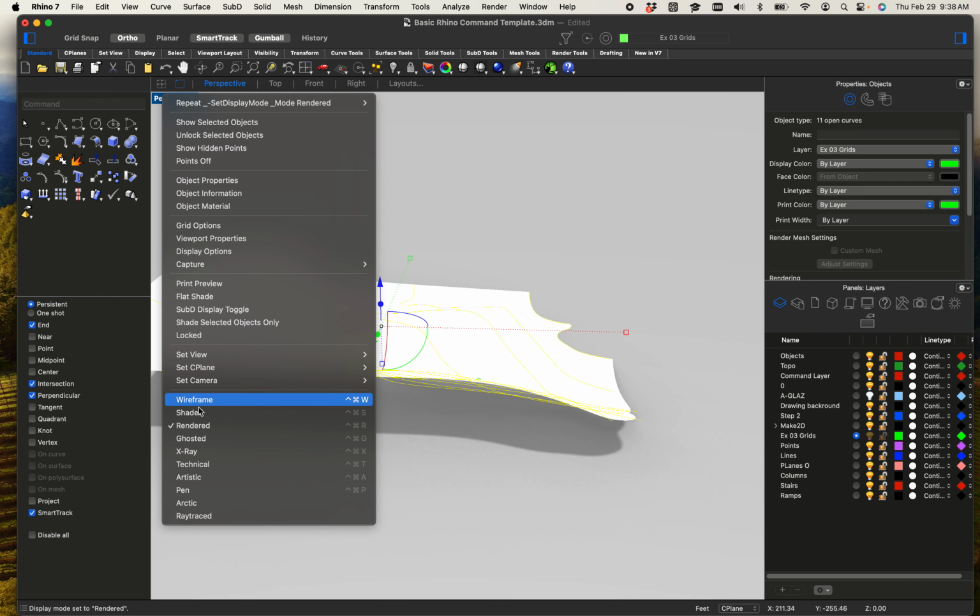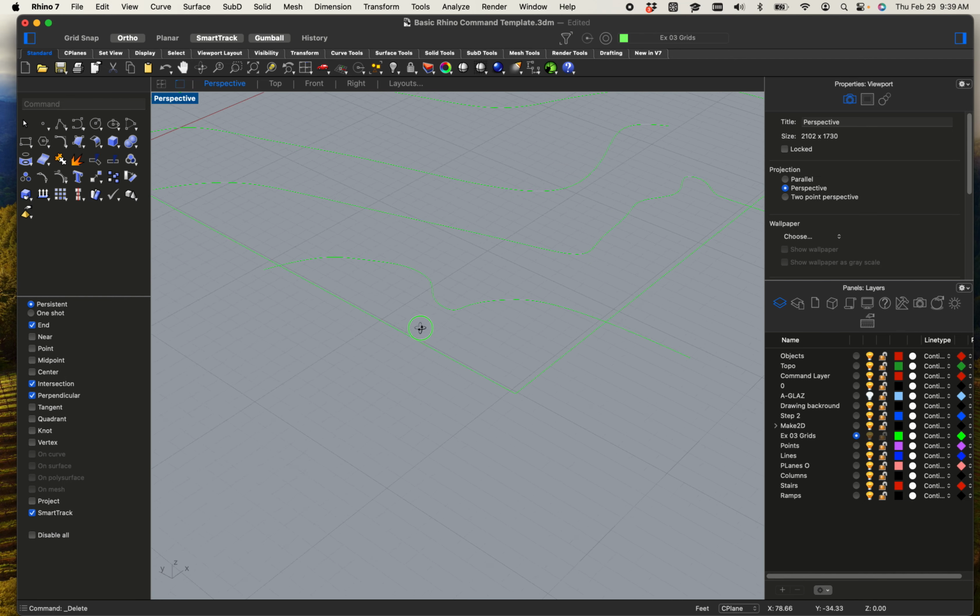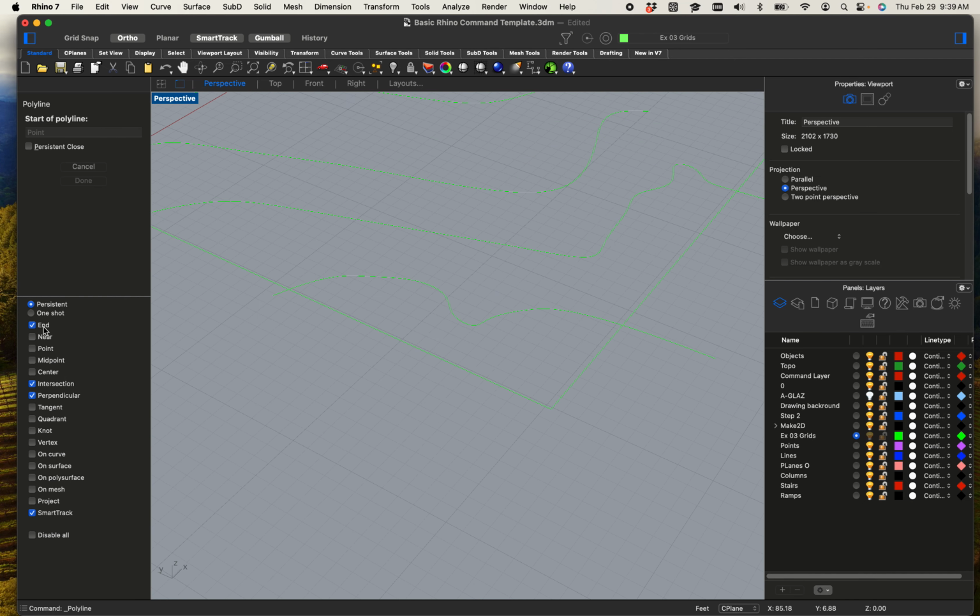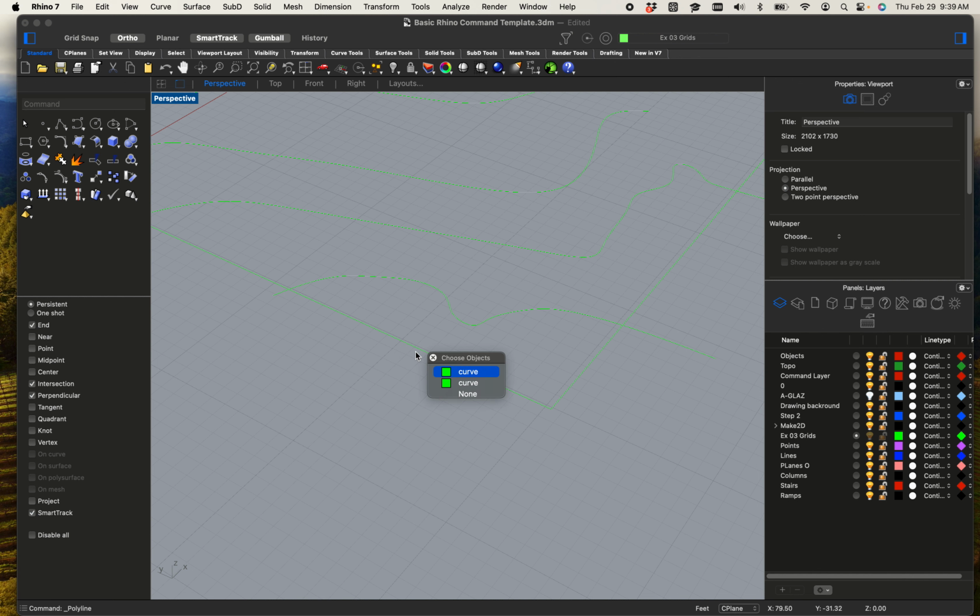And you can see how it left a hole because I didn't draw that extra polyline. So let's draw that extra polyline, at least on this bottom piece. That one should be fairly easy because it's already on the ground and flat. Okay, here's where Near will come in handy. Endpoint, and I'm going to just choose Near again just because I need it to be somewhere on that line. So I guess Near isn't entirely useless, right?